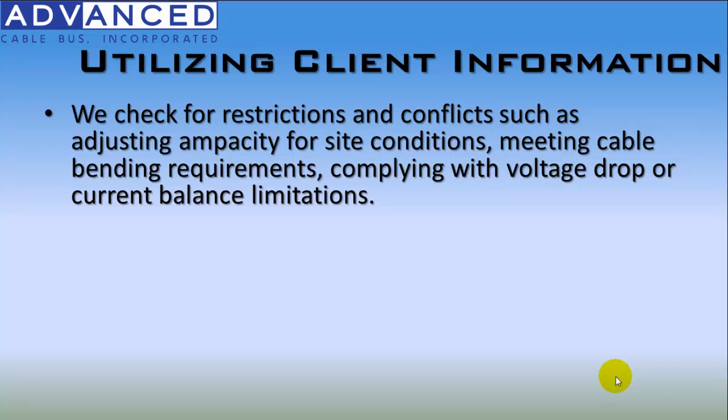We will have to design to make sure that cable bending requirements are met, not only inside the cable bus housing, but also in any termination space when the cable bus terminates into an equipment. We will also have to comply with the voltage drop requirements or any current balance limitations.